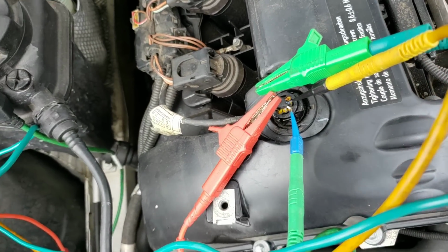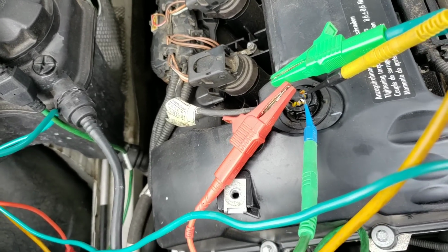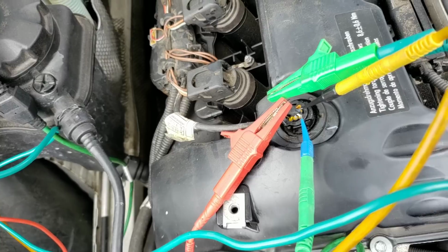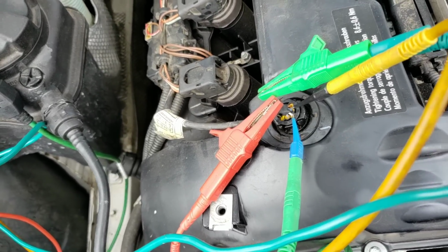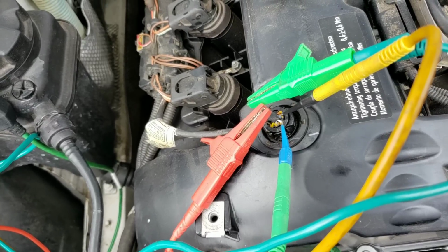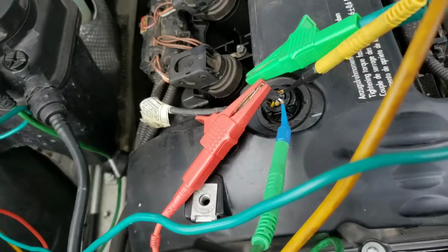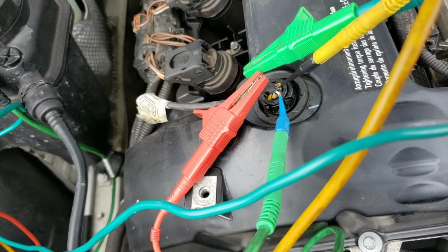But really, that's all you can actually do as far as testing. So you try to learn the Valvetronic limit positions. If it doesn't learn the limit positions, you just want to make sure that your shaft moves free. That will show in a different video. But the fact that this thing can actually bring itself up to idle and not be stuck in a no start condition means that the shaft can generally move. Generally. There's always some rules there that are a little bit different.